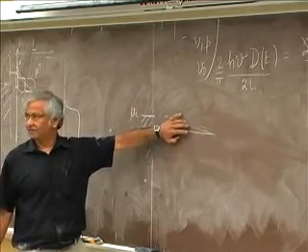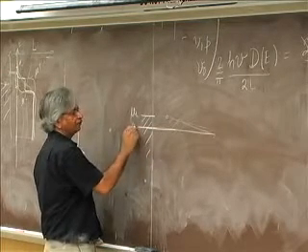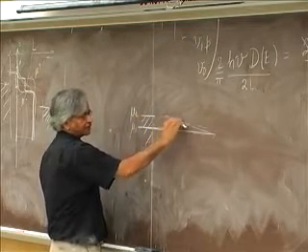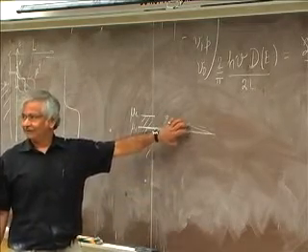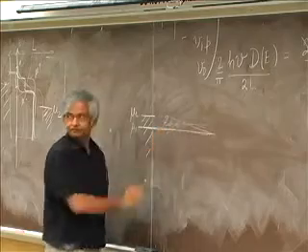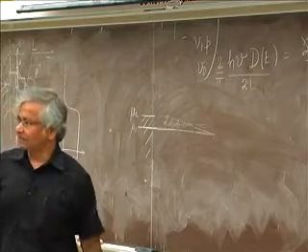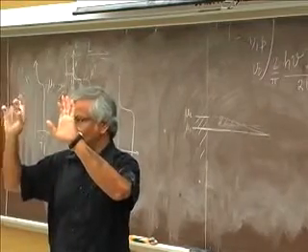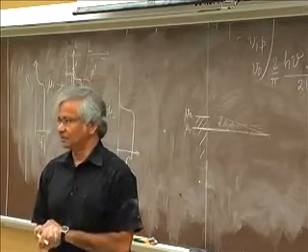Let's say this is the equilibrium mu 0, and you have put some voltage here to raise it, and you pump all these extra electrons in here. That would of course make this very negatively charged. And if it is negatively charged, when you solve it with the Poisson equation, this will automatically go up somewhat, and so on. All these would be at high bias. This is the point we discussed, that the saturation current of a transistor can get higher when you put a voltage, because of this requirement of space charge, that is, how to keep the electron density constant.